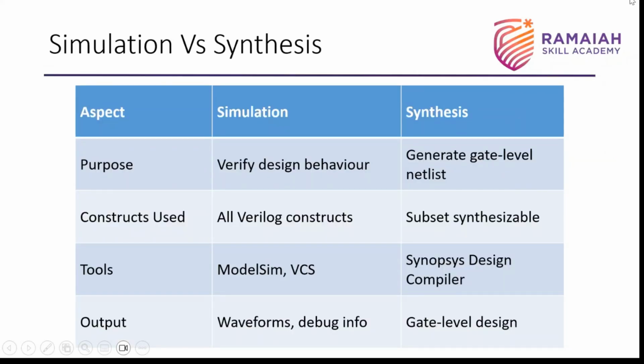Now, what is the difference between simulation and synthesis? Simulation, as you've seen just now, after writing a design, lets you verify whether your design is behaving as per your requirements. That is the main purpose of simulation. Whereas synthesis will convert your design into logic gates, in terms of AND gates, OR gates, NOT gates, etc. Simulation uses all kinds of Verilog constructs, like always and initial, but synthesis has some limitations on which constructs can be used, depending on whether they are convertible into hardware or not.